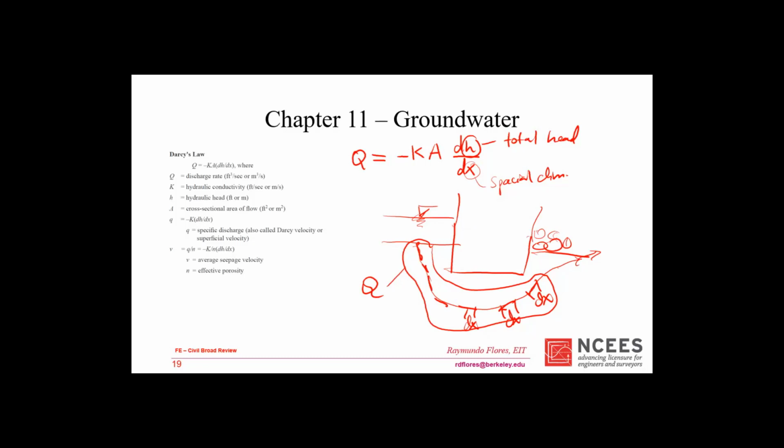It's amazing. But just to let you know, when you say dH, you're talking about the total head, which is some elevation, a y direction. So you're talking about the value of the total head at this point versus this point, with respect to the y direction. It has nothing to do with x, whereas dx has to do with the direction of the flow itself. This is very powerful, and you'll see this all over the place.